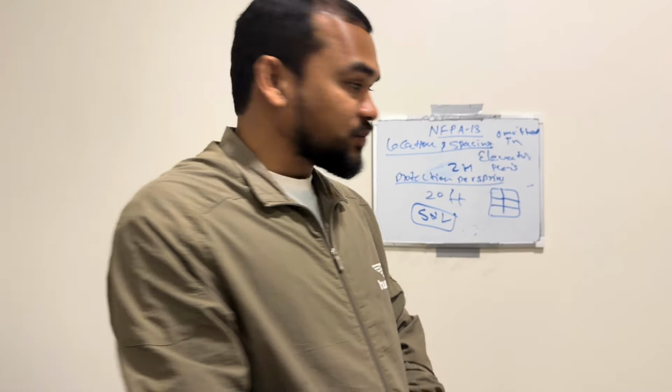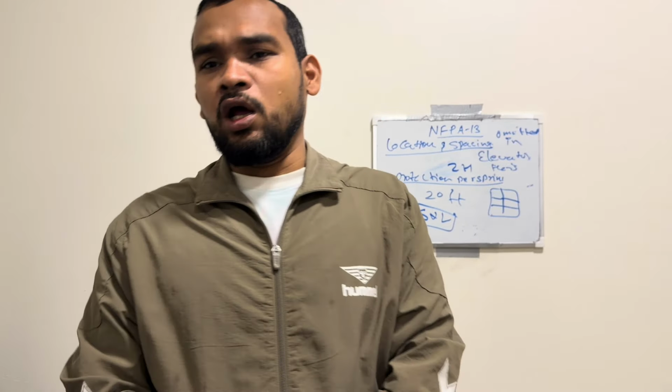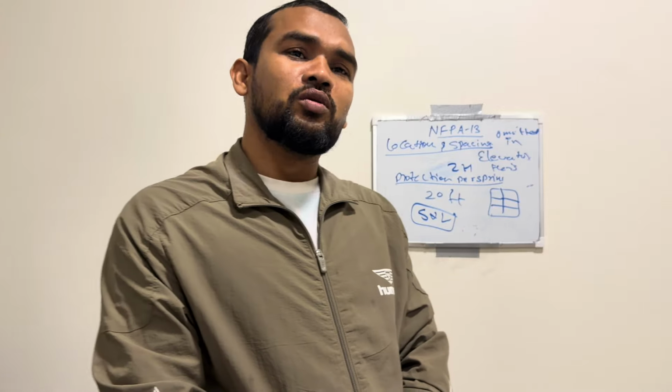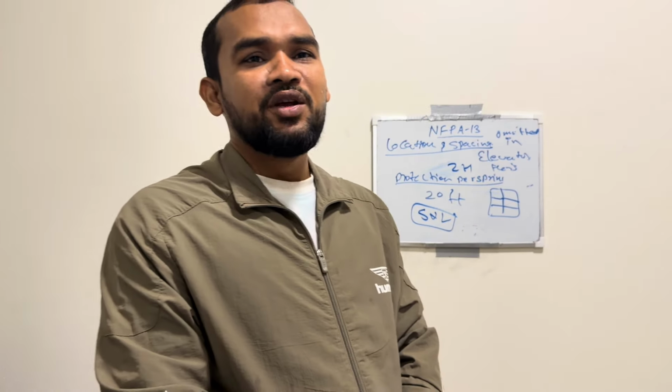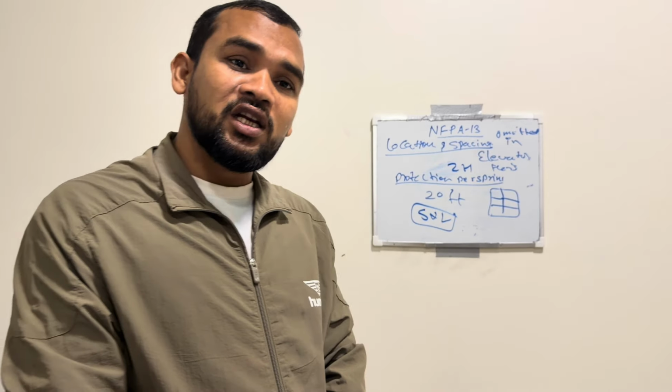pendant and upright shall use the table described in chapter number 10 in this case. And the distance from the wall shall be half of the maximum space from the table. For a small room, a sprinkler shall be up to 9 feet from a single wall. Curved surface should be measured from horizontal distance at the floor level. Minimum from wall is greater than or equal to 4 inch. Between sprinklers is greater than or equal to 6 feet unless baffles are installed in rack sprinklers.